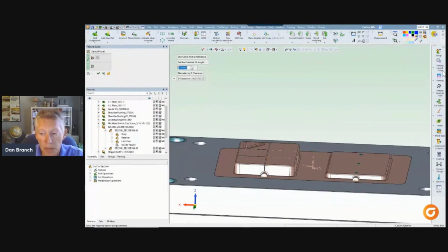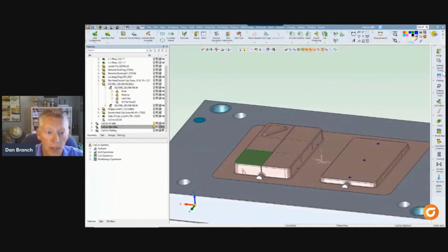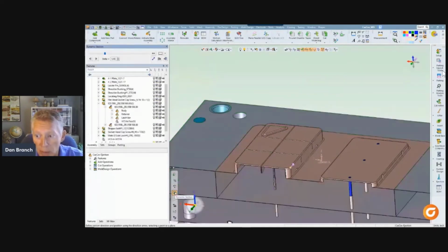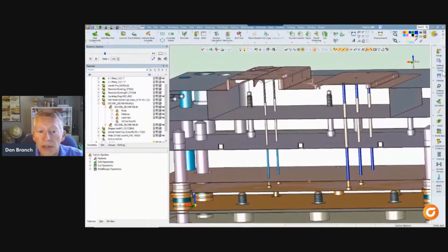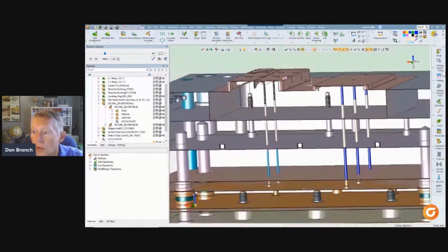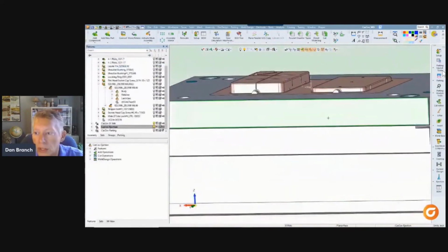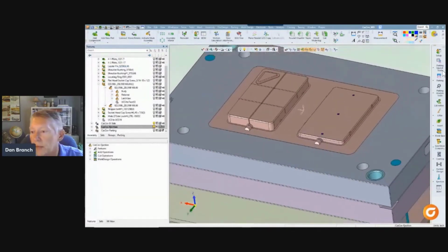Now, these holes get a special function because it's nice to have some extra options for them, like varying the depth of the clearance drill hole back from where the pin's going to break out on the part. So a quick section view with the hatching turned off is a good way to see how those holes turned out. And you can see all the different clear and fit diameters.